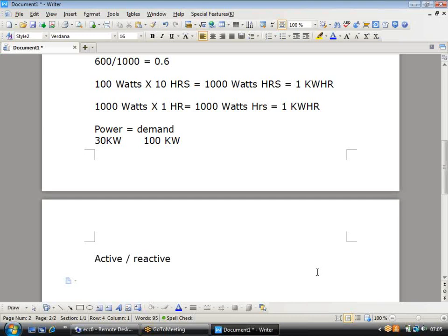But at the end of the day, when you are having certain machines in factories or some industrial or commercial applications, the electricity generation department, or whoever is supplying electricity, will also be interested in two components: active energy and reactive energy, okay. Active energy can be measured by the conventional meters, but the conventional meters cannot measure the reactive energy which is lost in the windings, okay. So sometimes you may have a separate meter, or in the meter itself you have one register which is showing the active energy and one showing the reactive energy, okay.